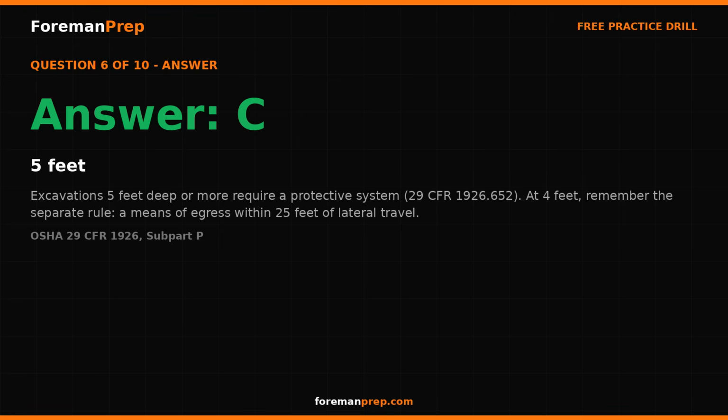The correct answer is C, 5 feet. Excavations 5 feet deep or more require a protective system, 29 CFR 1926.652. At 4 feet, remember the separate rule: a means of egress within 25 feet of lateral travel. Reference OSHA 29 CFR 1926, Subpart P.